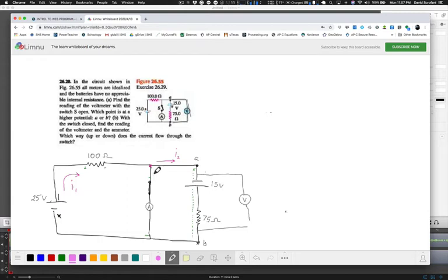And this current, which I'm going to arbitrarily choose as being down, I'll call I3, like that. Again, there's no resistance between these two points with a perfect ammeter, but I still have some current traversing that section of wire right there. And of course, I know by the junction rule immediately that I1 equals I2 plus I3. Great.